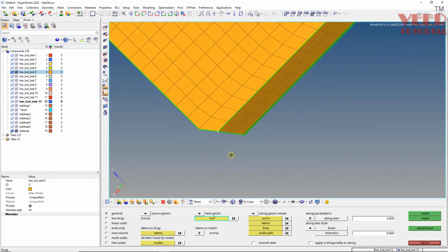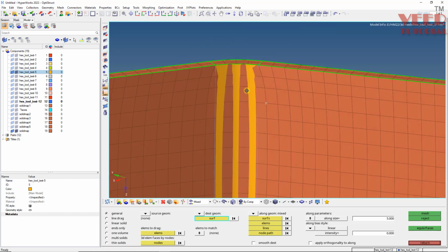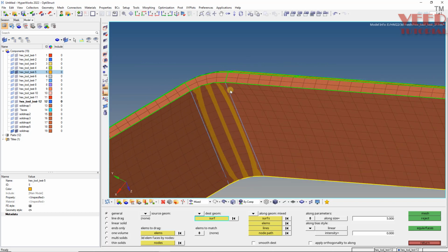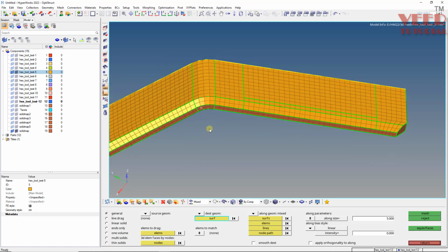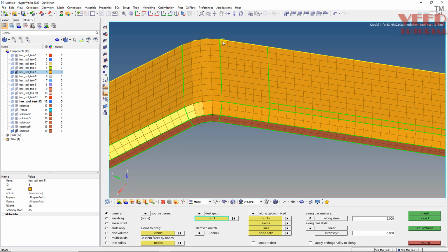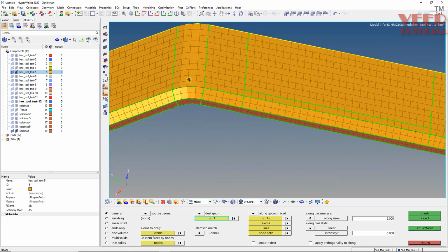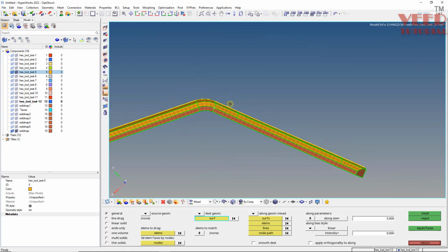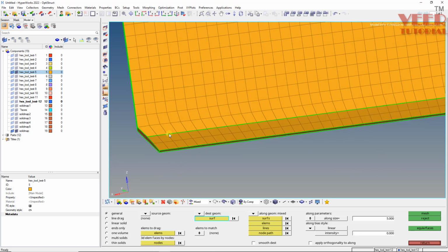and let's see whether this mesh is proper or not. Okay, it is looking good. Also from here, if you want a proper mesh flow at this fillet also, then in this case you will have to split this, do the mesh first in the right part of this fillet, then this fillet, and then the left part. So we have to do this 3 times, then it will capture this fillet properly from the bottom also. But to save our time, right now we are doing it this way. This is also correct. So some elements are a little bit oriented, so let's check the element quality here.